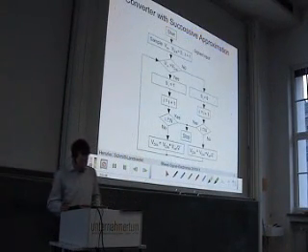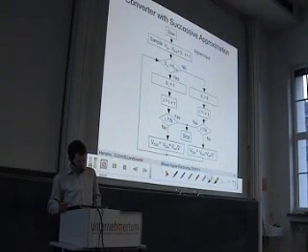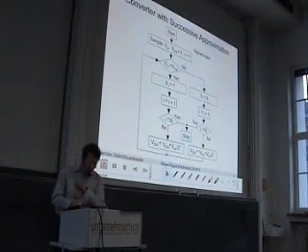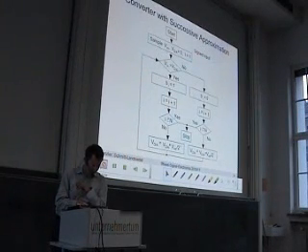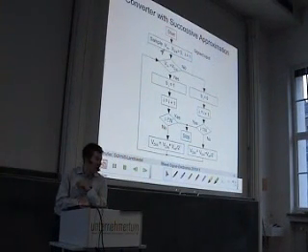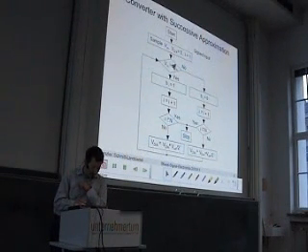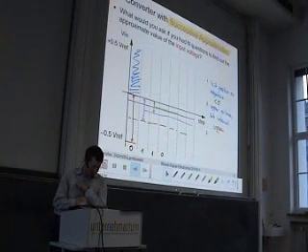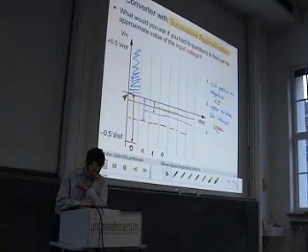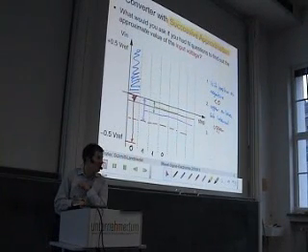So, to review this algorithm, I want to go through this flowchart. We start the conversion by sampling the input signal. So we say we have a sample of the input signal V in, and we have an internal signal. Here it is called VDA. We will see on the next slide why. We have an internal threshold signal which is set to 0. And then we ask the question, is the input signal larger than this threshold? And if you look at this slide, then you can see the threshold is set to 0 because in the first step we check for the sign.